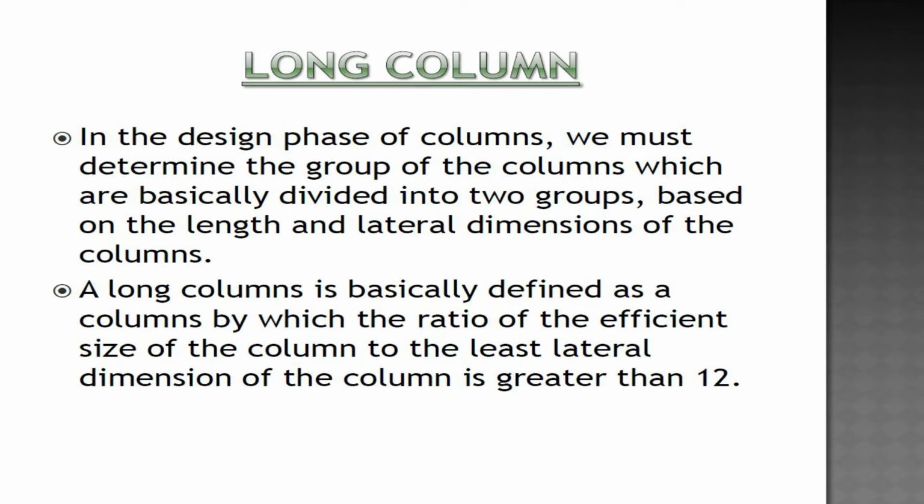Long column. In the design phase of columns, we must determine the group of the column, which are basically divided into two groups based on the length and lateral dimensions of the columns. A long column is basically defined as a column in which the ratio of the effective length of the column to the least lateral dimension of the column is greater than 12.